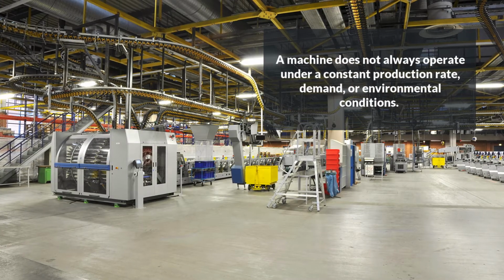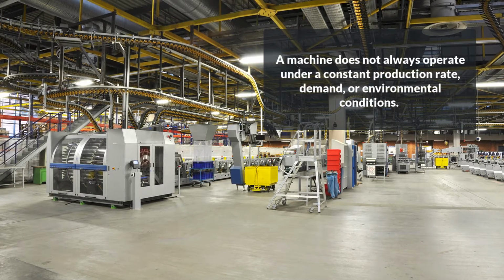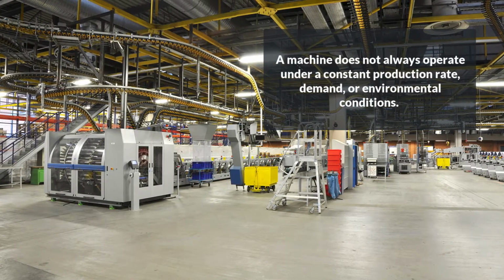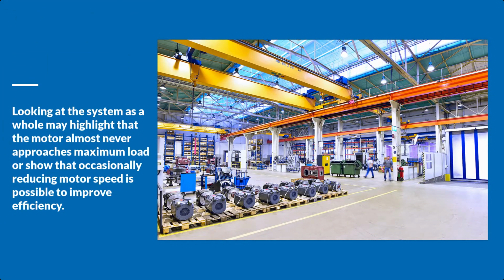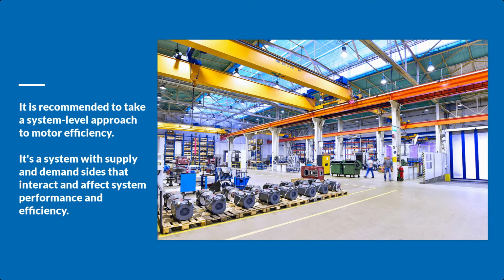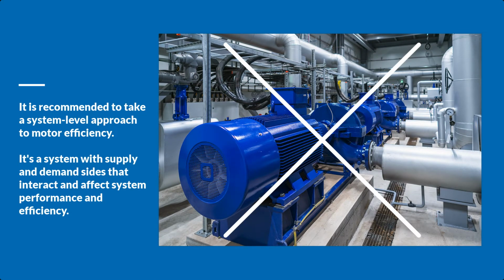Depending on the application, a system-level approach may show the machine does not always operate under a constant production rate, demand, or environmental conditions. Looking at the system as a whole may highlight that the motor rarely approaches maximum load, or show that reducing motor speed at times is possible to improve efficiency. The current narrative on motor efficiency is to take a system-level approach. It's not just a pump. It's a system with supply and demand sides that interact and affect system performance and efficiency.